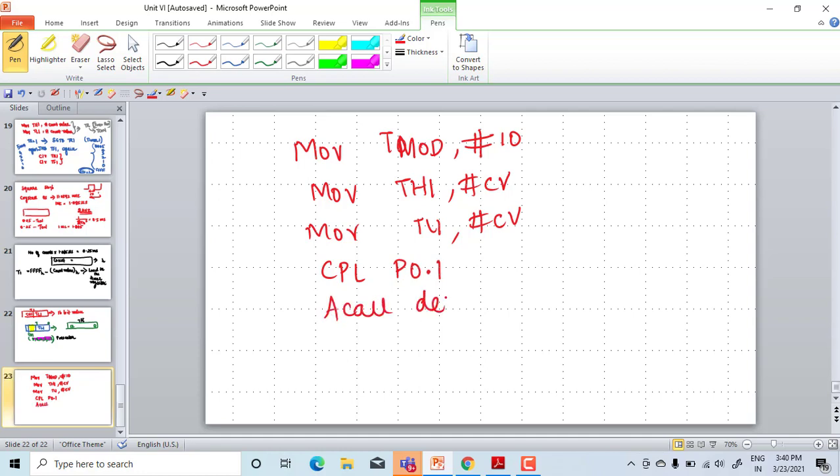Already you have called your delay. What is your delay? In the delay routine, what you need to do? First you need to start the timer related operation. Set TR1.